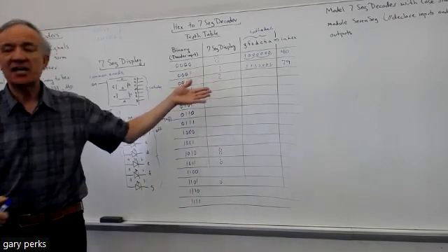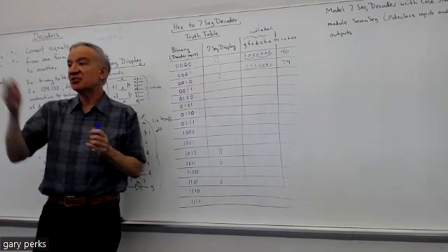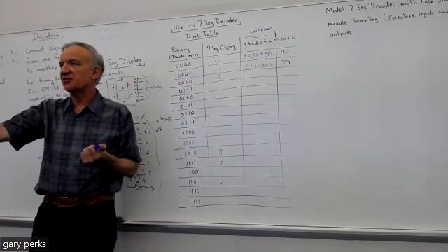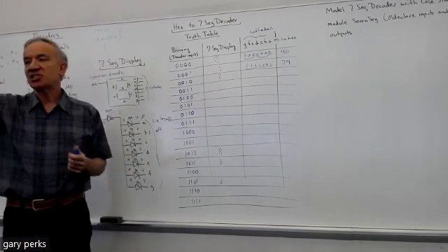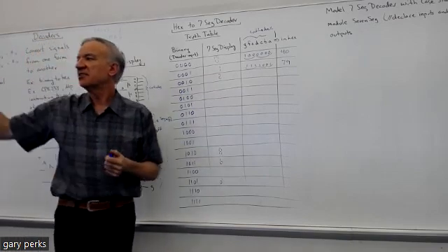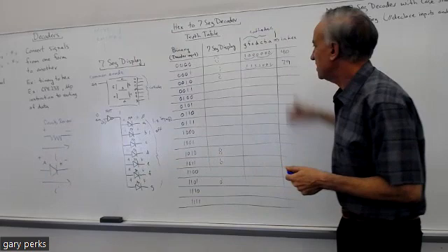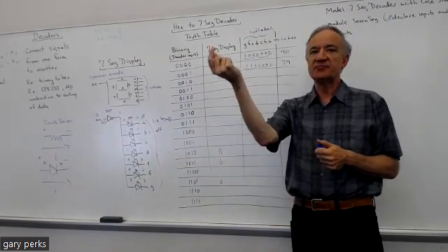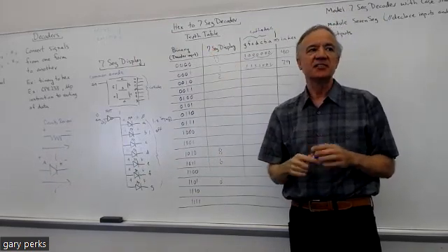So when you look at the timing diagram for this decoder, instead of looking at it in binary, which I think is what it defaults to, you can just change the base to hex. And then you can just verify that the hex is correct for that test case.